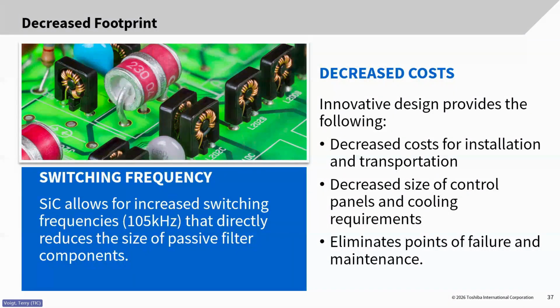It's best to connect power back up to the capacitors so they can mix the electrolytic solution inside the capacitors. The WC1 uses a film type capacitor, so that means you don't need to do that. So the shelf life becomes much, much longer on a film type capacitor versus an electrolytic capacitor.